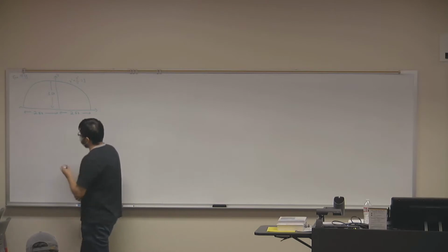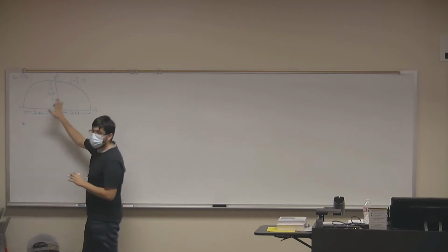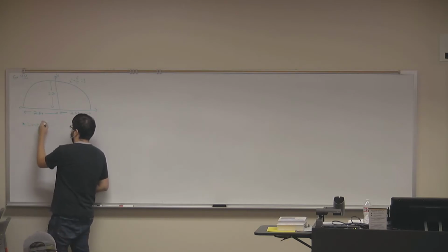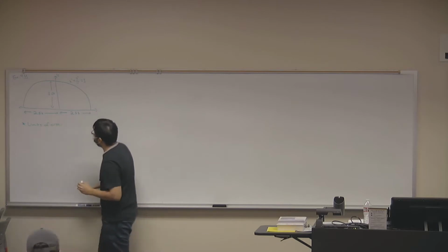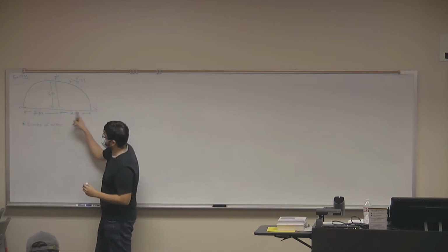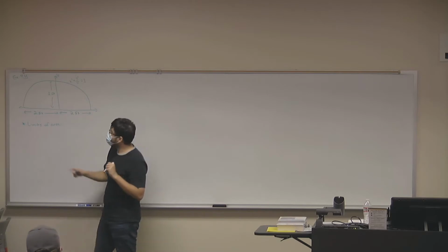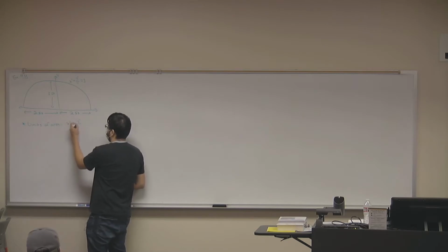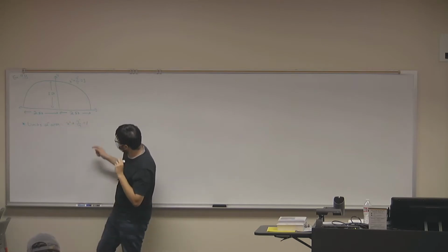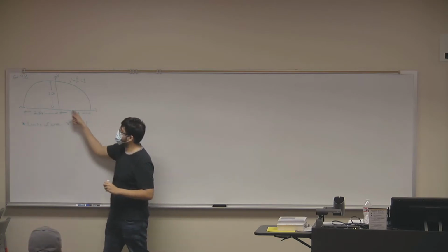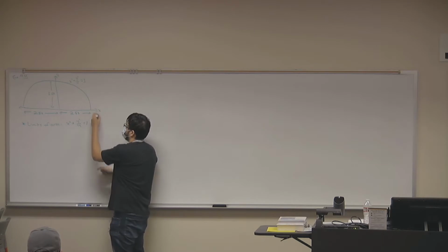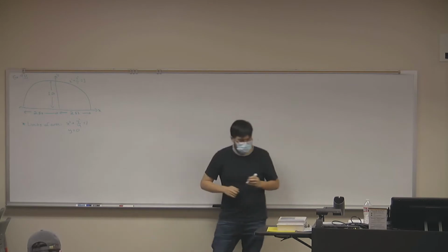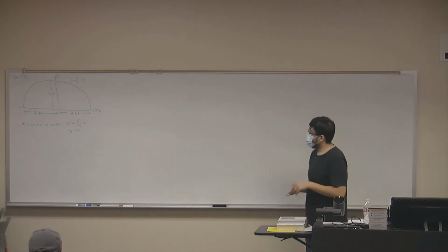Now, we mentioned that when we're dealing with 2-dimensional areas, we always want to make sure that we are aware of what the limits of our area are. So in this case, this shape, this half of an ellipse, is bounded by 2 curves, right? We have the curve of the ellipse, which is x squared plus y squared over 4 equals 1. And then we're also bounded by this line. What's the equation of this line that goes through the x-axis? Y equals 0, right? So our shape is bounded by these 2 curves. And we want to find the centroid.